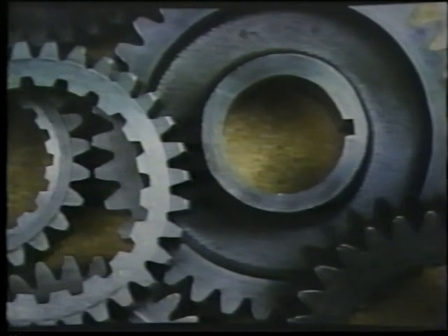You've seen examples of the major kinds of spur gear wear problems that you're likely to encounter in a normal transmission teardown and rebuild. Remember that these wear or distress signs are typical, but they may not always appear at the same time in the life of a transmission.